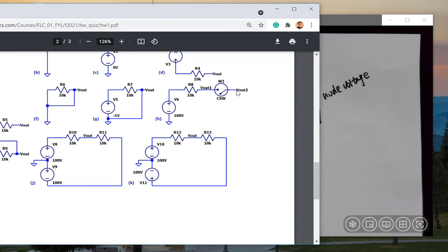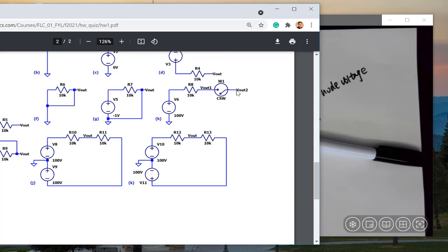If I just directly grab a wire, it's a floating wire, like this one, right? Can you say the voltage here is 0 volts? No, I cannot, because it's not 0 volts. It's just nothing. It can have a little bit of static charge accumulated on the wire. But if you measure it, it's going to be very close to 0.